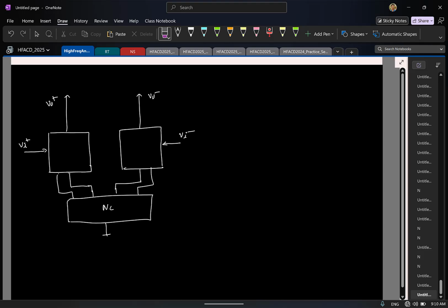So now let's try to find the noise in this. Again, let's look at a general result. To find the noise, assuming that the input impedance of the circuit is infinity, you just need an effective input referred noise voltage. So for finding the input referred noise voltage, what is the value of the source resistance we use?